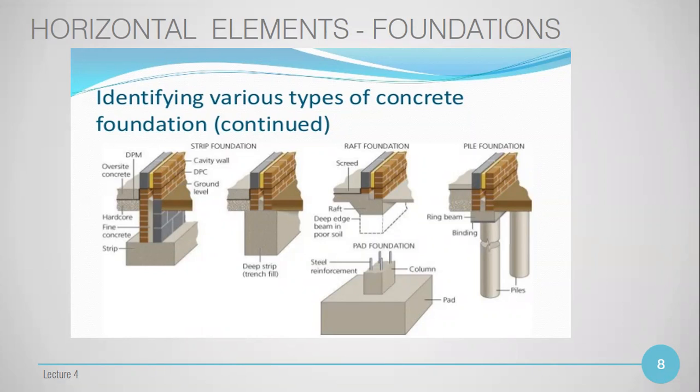So we have wall or strip footings, and they're usually used for residential buildings, since the distance between bearing elements is not so big. Another type that can be used is isolated footings, but they're usually used for large structural distances. In some extremely difficult and complicated cases, we use slab foundations in order to provide stability for the whole building against underground water.